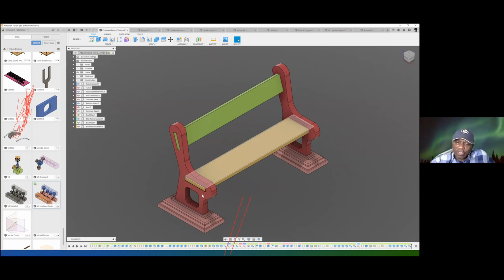So all the drawing is done in one, and all we did is replicate that drawing and put it here. That's all. There's no new work done here. Once you have finished a component, you can make 2 copies, 10 copies, 50 copies, 100 copies. It will just be the same thing, more of the same. You can see these 2 things are of the same color. And if you go to the browser, you see ARM1 is of the same color as ARM2. ARM1 is the identifier ARM1, ARM2 is the identifier ARM2, but both of them are the same color because they are referring to the same component.